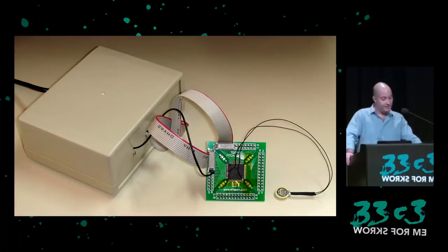The timing of ACP responses is different on a chip with valid RAM compared to the previous chips that I'd glitched before. I didn't confirm whether the cause of the timing difference was due to a different oscillator configuration or just a different software path. But by adjusting the timing of the glitches, the executable code payload runs as it did on the previous chips. So now we can read the RAM contents of a valid ACP, including the category keys, if the set-top box had current authorization, as well as the seed keys that are used by this ACP to decrypt EMMs. With a valid category key, ECMs can be decrypted and a correct working key can be calculated for any channel.